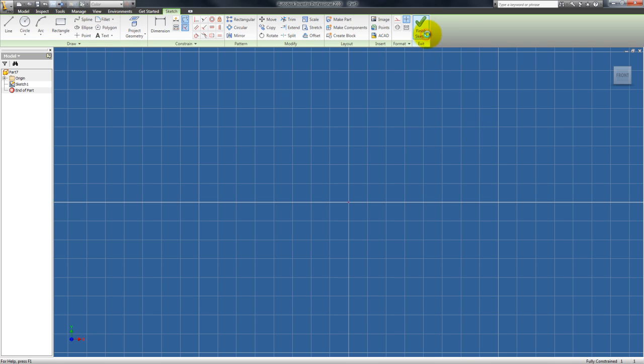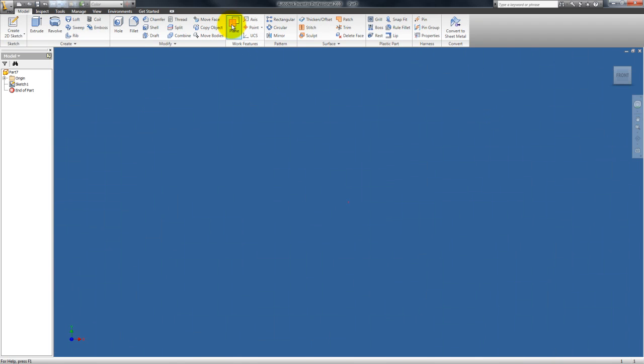So if we go over to the Model tab, the work features. This is extremely useful. I found this very useful in doing the complex shapes in that bike that I built. Most specifically the frame and all the features that had to loft, sweep, sort of any of those features that are really complex and have many different cross sections. For example, you're going to need work planes, axis, points, and to play around with the UCS.